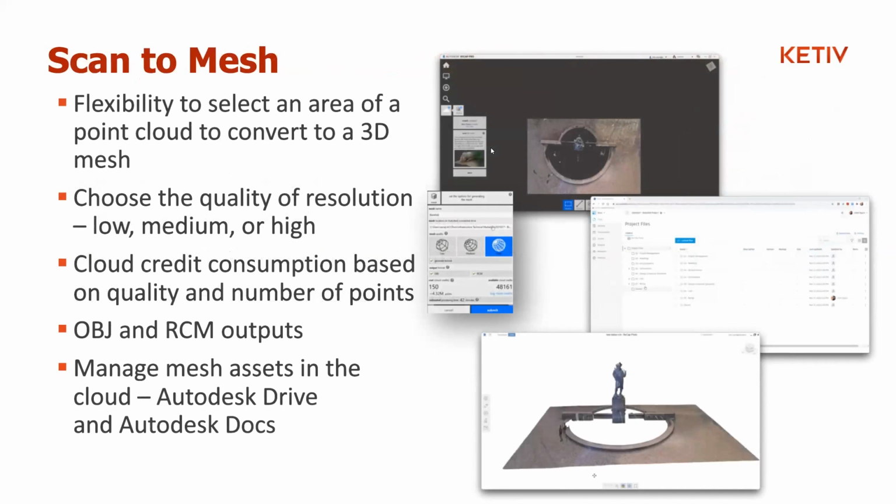So circling back to those big three I talked about a couple slides ago. Scan to mesh was a beta feature in ReCap previous to 2018. The process is very similar to how it used to be. You have your point cloud, your RCP file in ReCap Pro, and you can select the entire point cloud or a small portion of it and convert it to a 3D mesh. This is done by cloud processing. You'll pick a location on Autodesk Drive or Autodesk Construction Cloud, and it'll publish that mesh file there.